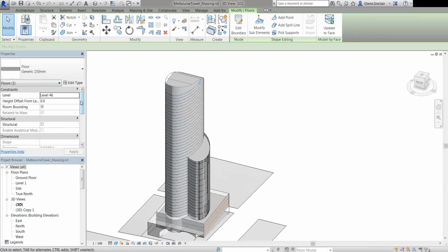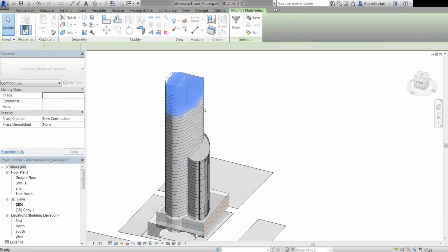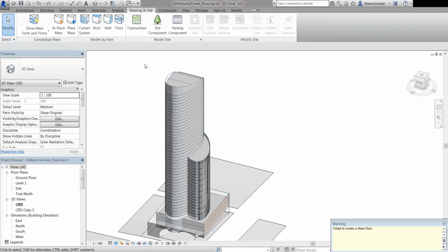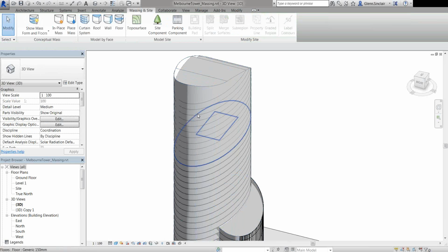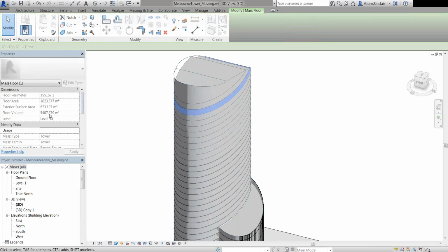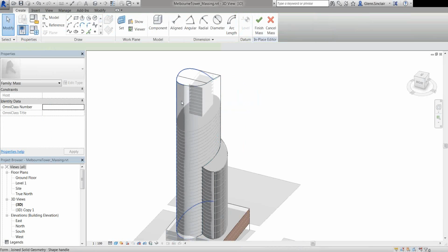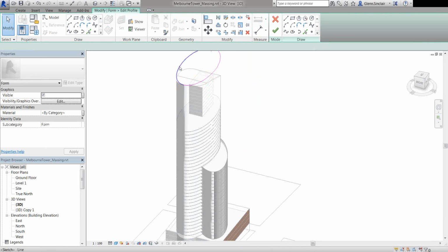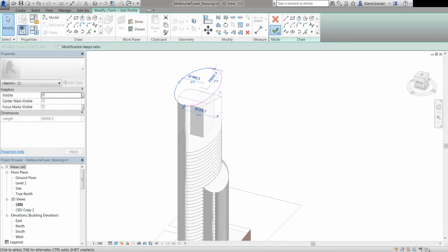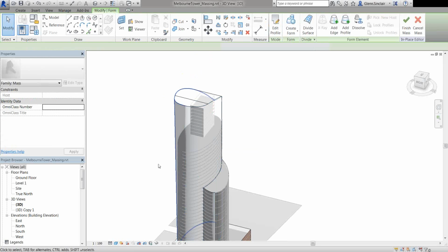So if I get my shape here, what have we got at the moment? So level, I've got the actual floor. I'm going to get rid of those concrete floors so we can see. So there we have the level, and if I edit the shape to whatever crazy edit I wanted to do, top profile, larger, smaller, change shape, all of those floors are going to update, and then all of the areas should follow along too.